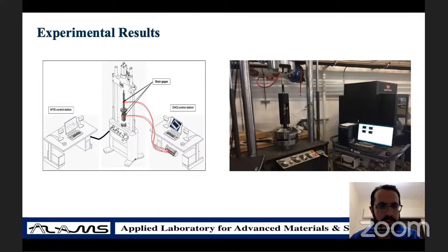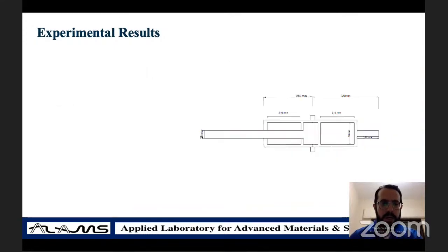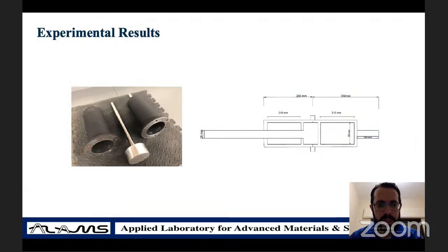So first of all, after fabricating the system, we started to apply some different loading protocols. We used the universal testing machine to install the specimen between the two heads of the machine, and we attached the needed strain gauges and LVDTs to measure different performance parameters, such as strains and loads and so on. So as you can see here, this is an actual picture of the system, the fabrication and so on.